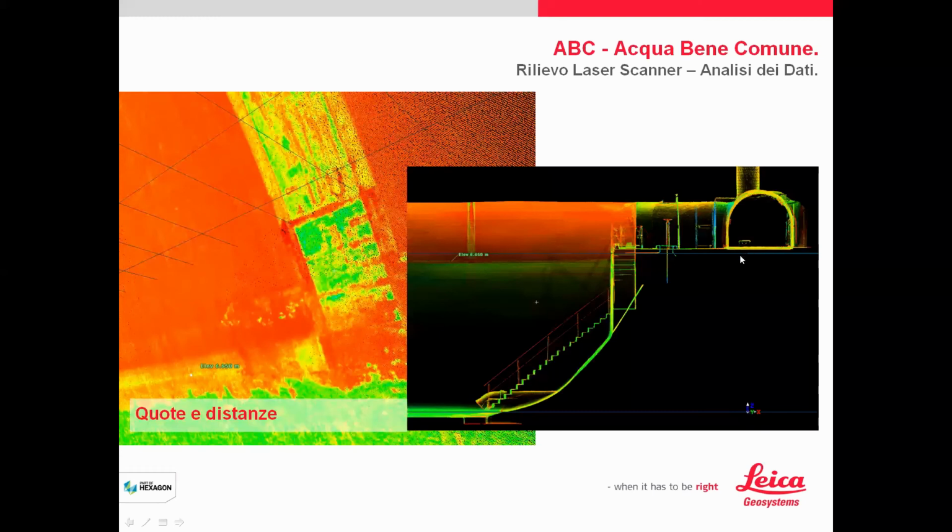So the 0 is 7 meters down this line. So I fixed my 0. The UCS is the user coordinate system. So I have changed the origin of the system to 7 meters down this line, to have all the elevation points that I pick on this point cloud correctly oriented.